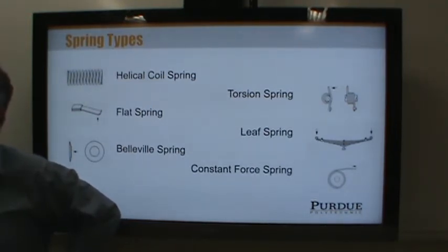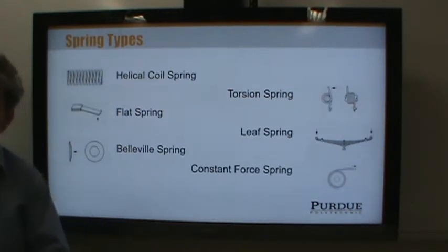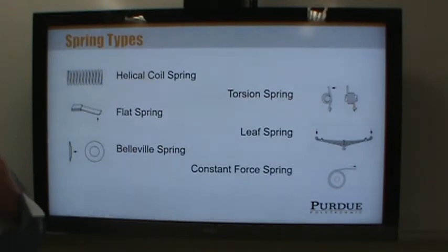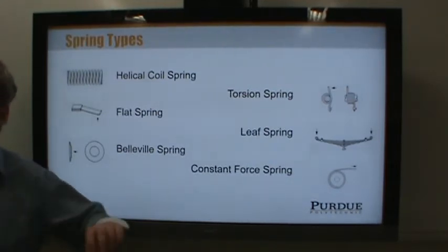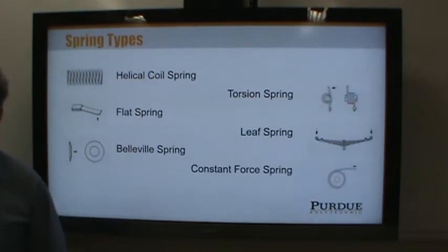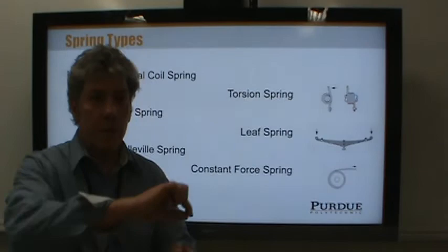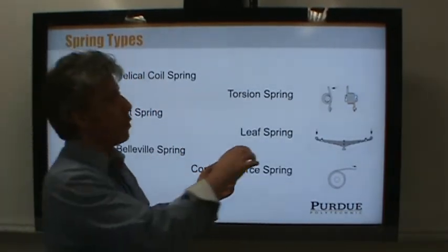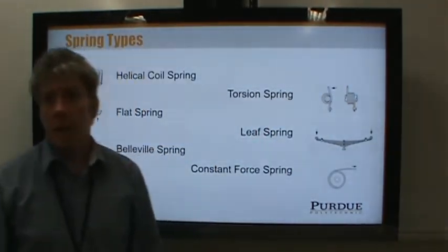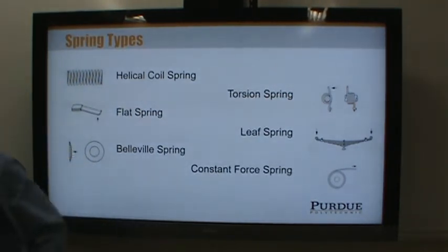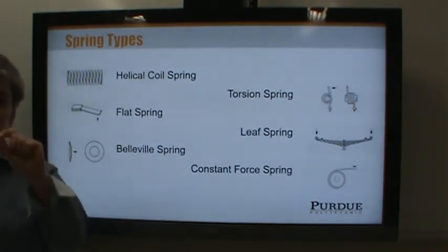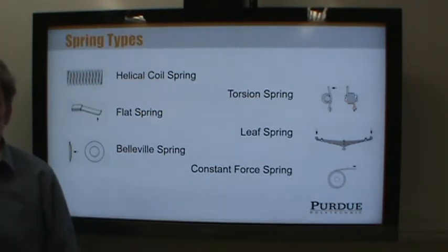Well, the recoil for a lawnmower is different. With the lawnmower, as you pull it and deflect it farther and farther, the amount of force actually increases. It's got a low spring constant, that's why it doesn't feel like a lot of difference, but the more you deflect it, the stiffer, the more torque it's actually putting out. That type is interesting because it's not a simple torsion spring. It's actually spiral wound, so it's flat. So all the coils are in one plane, essentially. So that's an interesting spring, but it's not exactly a flat spring. Now it is thin, and so it acts more like a flat spring.